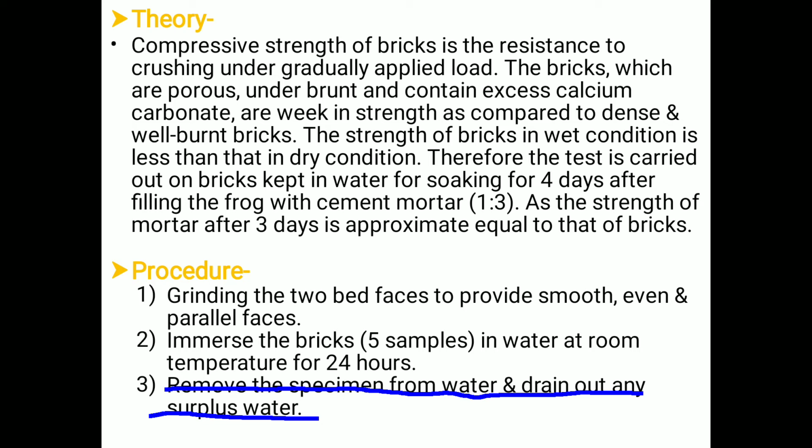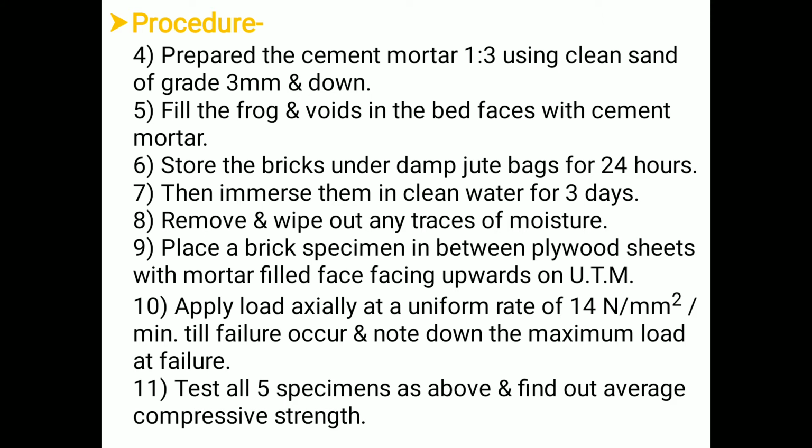Then we have to fill that particular frog. Prepare the cement mortar with 1:3 ratio using clean sand of grade 3 mm and down. Remember that mortar consists of cement, sand and water. The ratio is 1:3, which means 1 part of cement to 3 parts of sand.